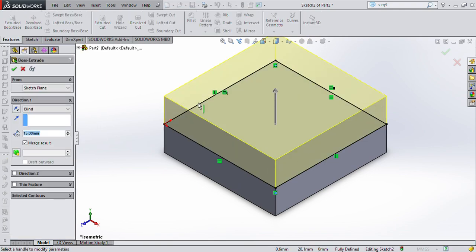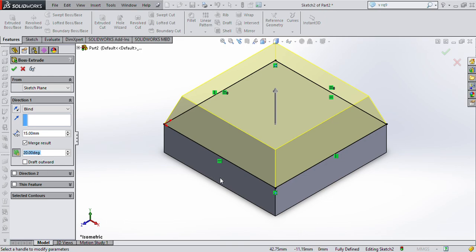Extrude, we are going to make a conical part here. The angle which I'm looking for is 20. So I have to select here draft on, okay, and here the degree you should select 20. Okay, 20 degree. Height which I should build is 27, sorry. Okay, now I made this part.